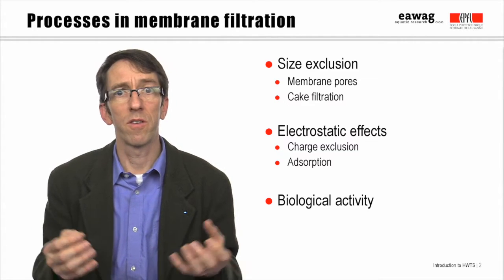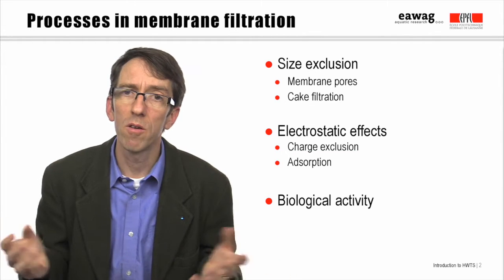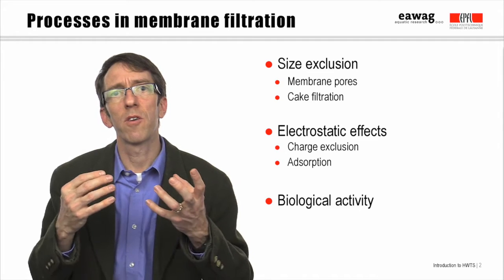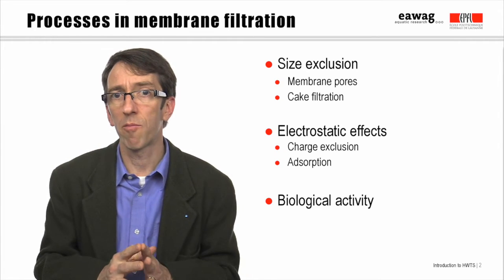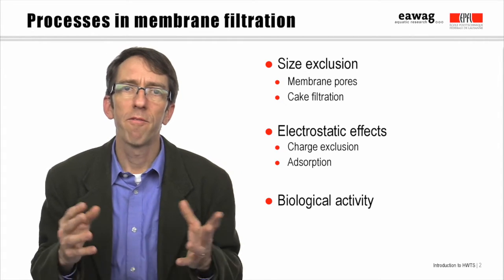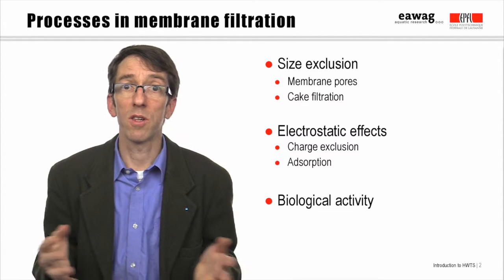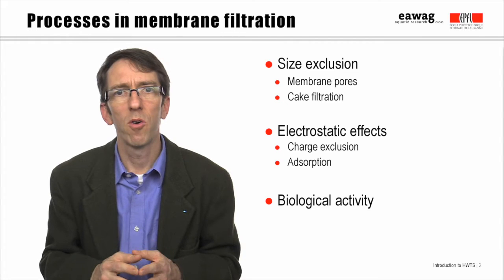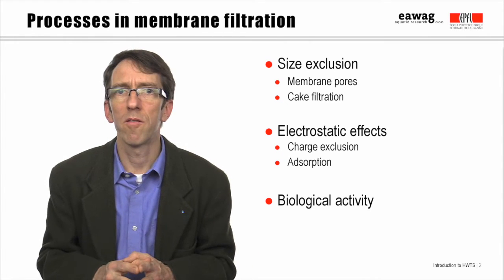If the charge is the same, they will repel each other, and if the charge is opposite, the particles can be attracted to and adsorbed on the membrane surface. Finally, membranes are biologically active, and that can have large impacts on the removal both of pathogens and dissolved compounds.